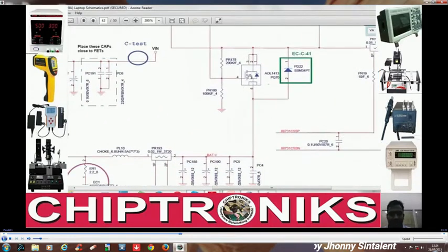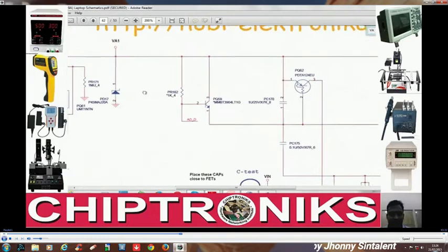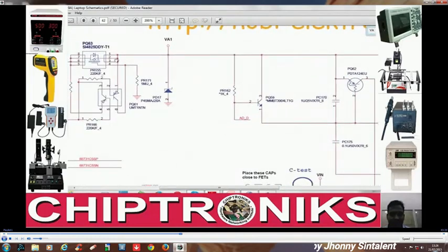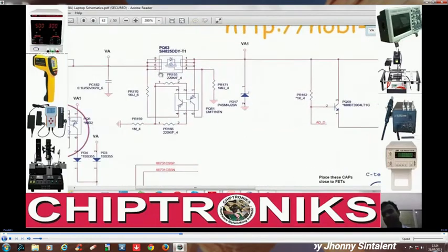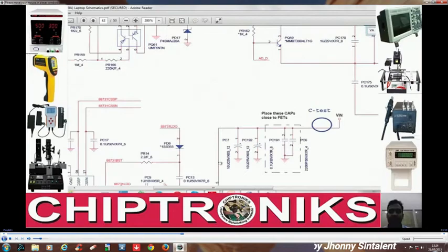Yeah, in the schematic diagram, as we told, VA1 is generated over here. This is a P channel MOSFET, but we know in a P channel MOSFET, if the input is connected to the source, then in that case VGS has to be negative. But here the input is connected to the drain, so it will act as a diode. Right, it will act as a diode, so current will flow across this. VA1 is generated over here.